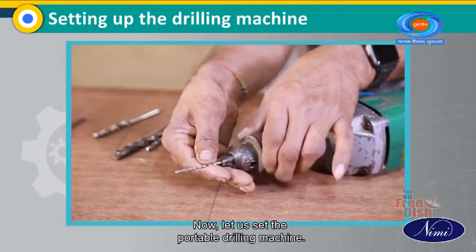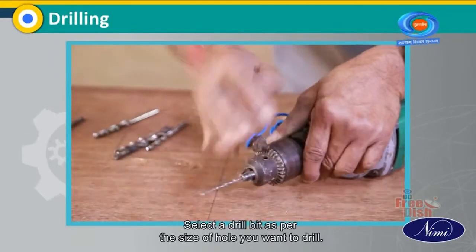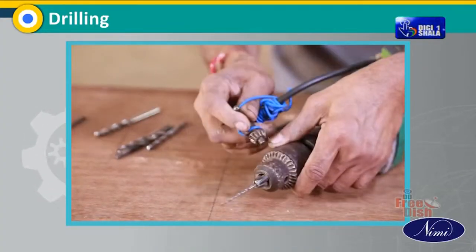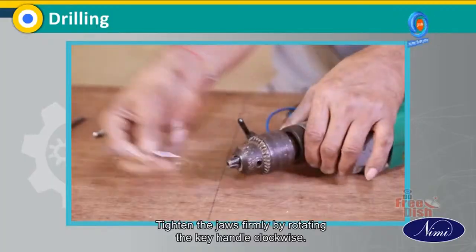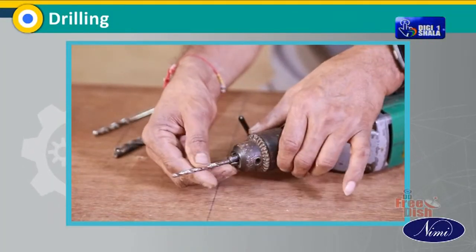Now, let us set the portable drilling machine. Drilling. Select a drill bit as per the size of the hole you want to drill. Insert the key into the chuck hole and rotate anti-clockwise to open the jaws. Tighten the jaws firmly by rotating the key handle clockwise.